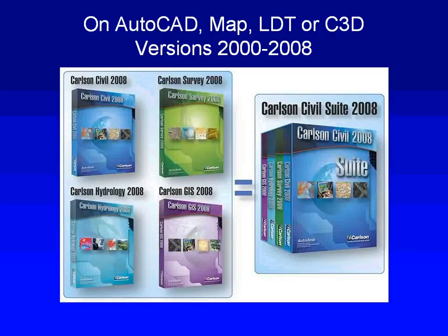If, however, any of those commands generate external data, then what's going to happen is that you're going to be writing to the Land Desktop project data set. So I just want to be very clear on that. And you can actually do that now. Carlson will be writing to its data set, but if you run a Land command, generate a surface or something, it'll write to the Land project. But that's actually a possibility if you plug into Land.